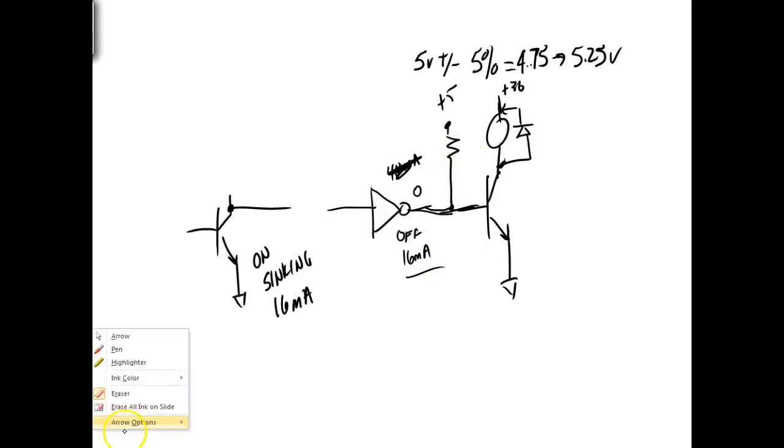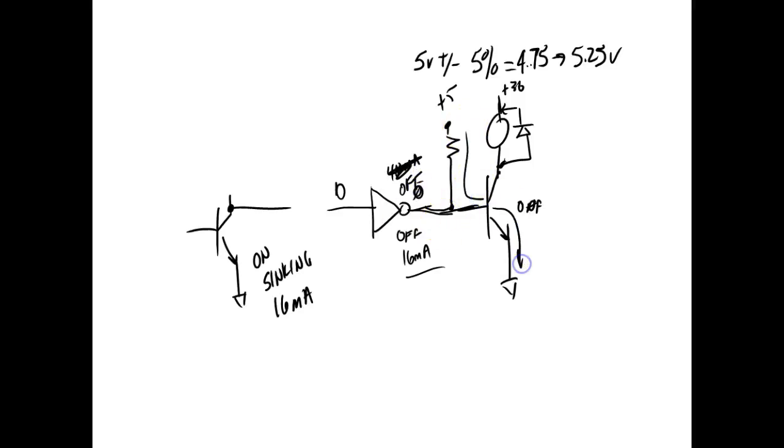So when this input right here goes to a 1, this goes to a 0, the transistor cuts off, and of course the relay would cut off. When I put a 0 right there, this guy here can't output a high, but we don't need it to. Y'all understand? So the output of this guy here turns off now. It's not connecting the bottom of this resistor to ground, and now this guy can turn that transistor on.